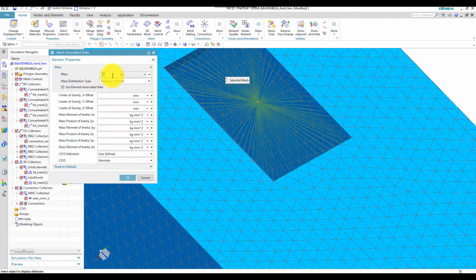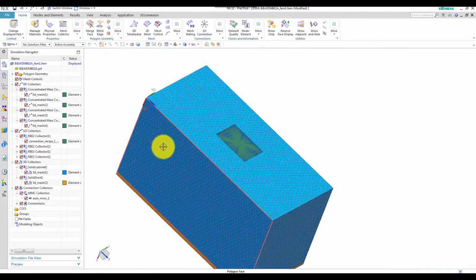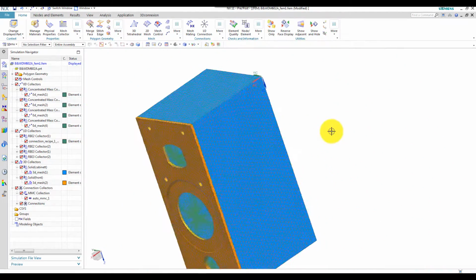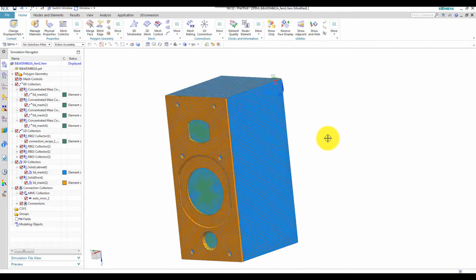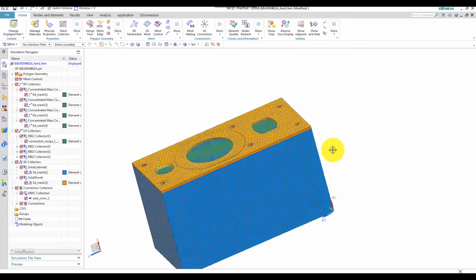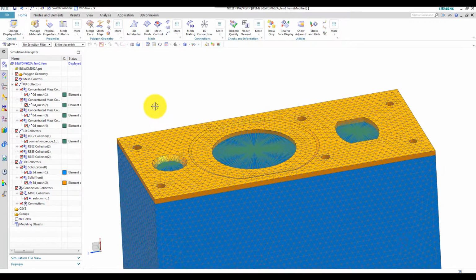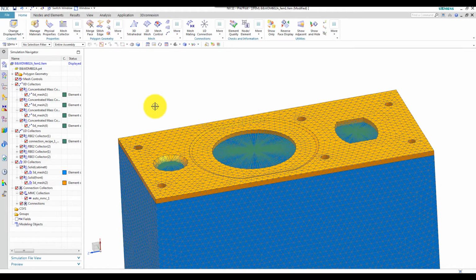It has a mass of 0.2 kilos. So this is my finite element model. It's connected, and it has RB2 elements with concentrated mass elements in the center, representing the loudspeaker elements. So let's see how we can do a modal analysis of this initial design.